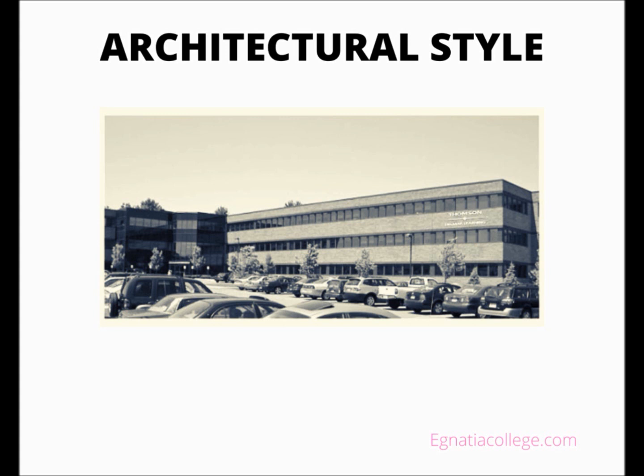Larger buildings require greater strength. The weight of the materials required to build the School Edition is many times the weight of the materials to build even a large house. Also, the external loads, wind, snow, etc., on a larger building are greater than those on a smaller building. All these greater loads require stronger structural members, more precisely engineered construction methods, and fastenings that transmit the loads from one structural member to the next. This usually dictates the use of structural steel and reinforced concrete for the structural elements of the building, the frame and foundation.